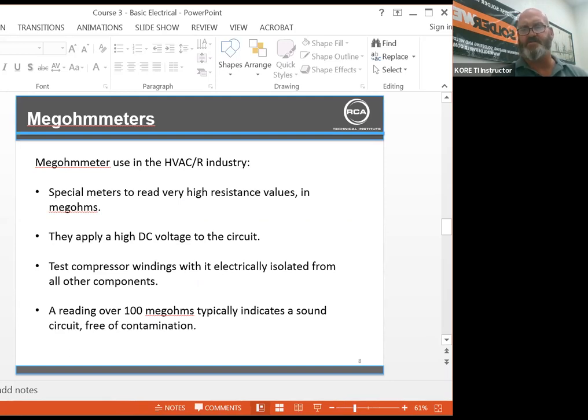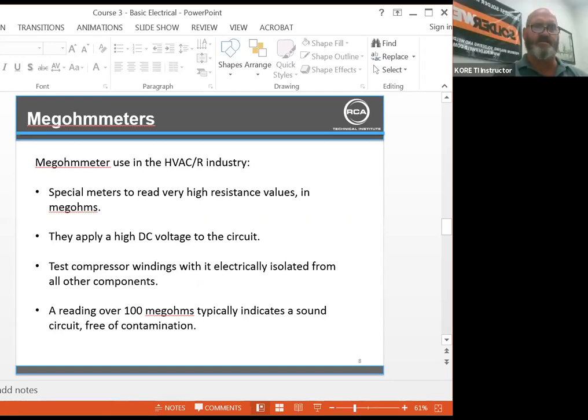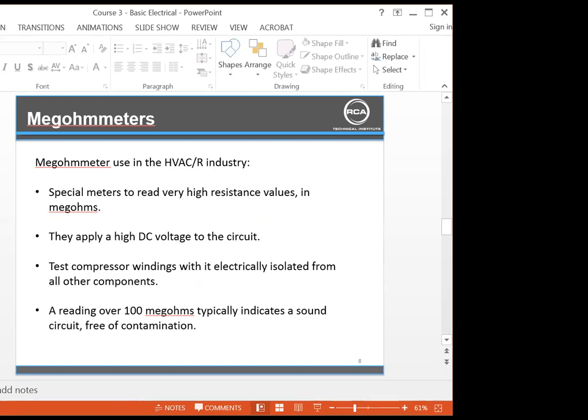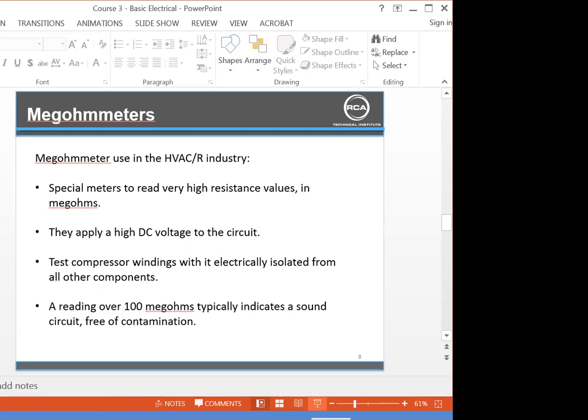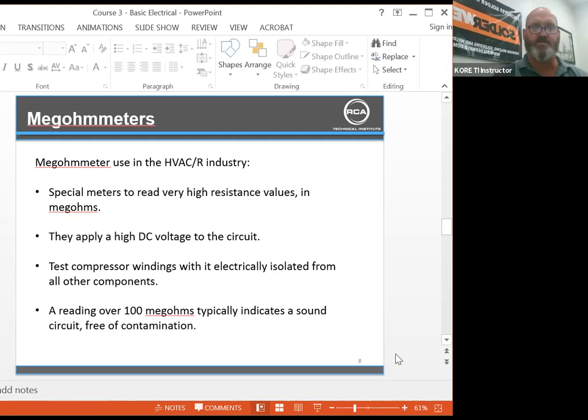Is Julian with us this morning? I am. Yeah, have you used a megger? I have. And how does it work? Hook one up, one lead to the chassis, and then the other one to the wire. And you send the signal through it, and it sends that, like you said, like 10,000 volts through it. And it checks the continuity or the resistance, I guess, of the wire, the integrity of the wire, and lets you know if the insulation's gone bad or if you need to replace it or not. Awesome. So did it save troubleshooting time?